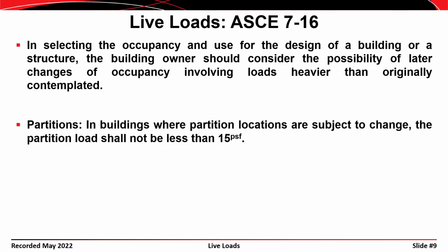Okay, there's also a discussion of partitions, and partitions may or may not be considered to be a dead load or a live load. If you go back into older specifications, I'm not terribly familiar myself, but I think if you go back to something like the Uniform Building Code, you can see examples where partition loads were considered to be dead loads at one point.